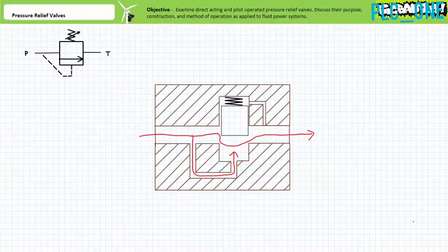Similar to our previously examined primitive pressure relief valve constructed with a check valve and biasing spring, at load-induced pressures below that sufficient to unseat the piston, the direct-acting pressure relief valve would remain closed. At pressures above that sufficient to unseat the piston, the direct-acting pressure relief valve opens, provides a relief path for pressurized flow. Pressure in this system is again limited to a preset maximum.